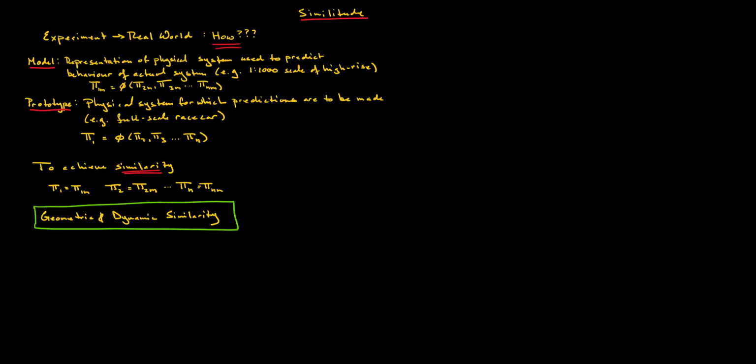And so using Buckingham Pi and the method of repeating variables, we can come up with a dimensionless relationship using these dimensionless pi groups, and we can express it as pi1m, with the subscript m for model. So pi1m is some functional relationship of pi2m all the way to pi nm, where we have n dimensionless pi groups. And now what we want to do is go from the model to the prototype, or vice versa, but typically we go from model to prototype.